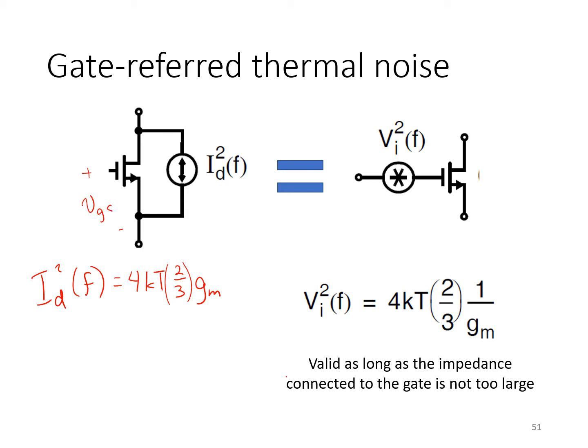small signal gate source voltage, then the situation is a little different, because if we try and improve the noise performance by decreasing gm, we're also giving rise to a smaller current signal at the output, gm times VGS. And so, sure, we might have less noise at the output, but we've also got less signal. And probably what we really care about is signal to noise ratio.